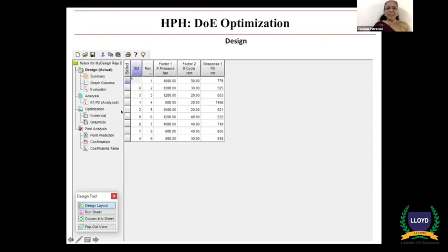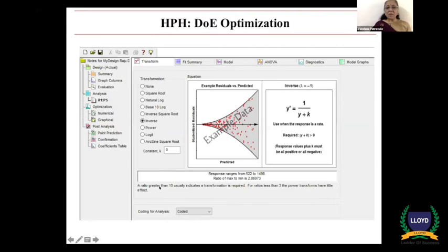Then Design Expert will give you this design wherein it will say which parameter to be used in which run and what is the response which you expect. So this is the response which the software has given you. Then you do all these runs. 3 is to 2 means 3 into 3, that is 9. So run 9 experiments and get the results.